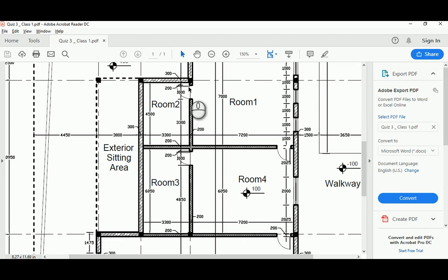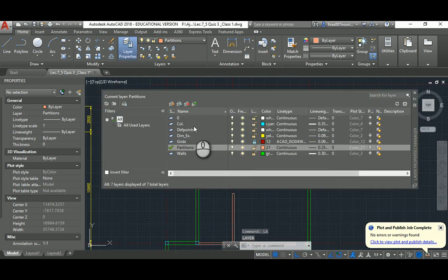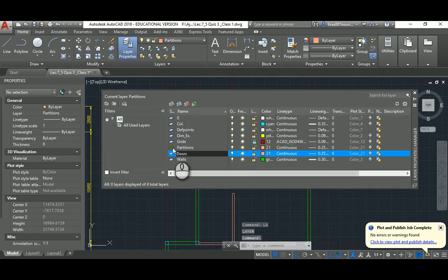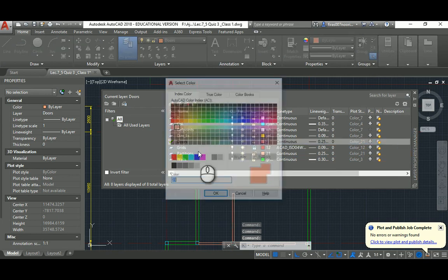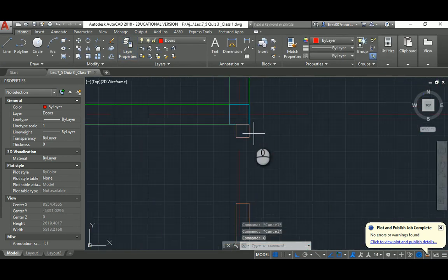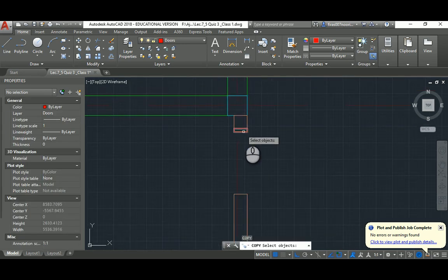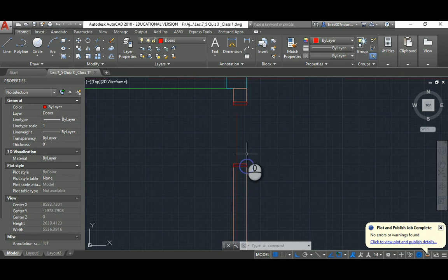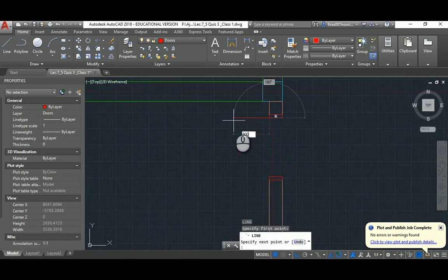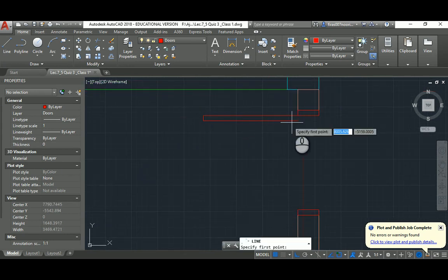So that's it. Those are the walls, and we can go ahead and draw those walls. So I will do so, and as we agreed, even if we have it drawn here, you should draw it the correct way. So I'm gonna go layer, new, and then doors, current that, and probably make it less than that, maybe 18. And I'm gonna offset that 50 mil, rectangle, remove the construction line, copy that guy, and it's 1000 and we lost 250 of it, so this is a 900 mil with an offset of 50 down, and then an extra 2 lines with a circle.